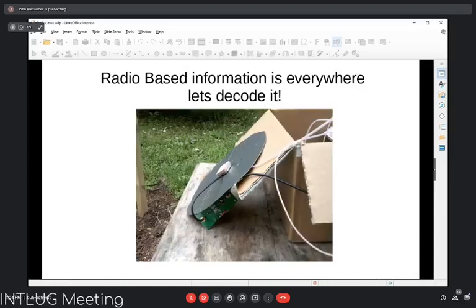So this is an example of the antenna they've used to pick up that information, right? This one's actually not, or certainly no dish, right? It's a GPS antenna, like some of these but a bit bigger, and it's just sitting on a bit of metal sheet to act as a ground plane. They're literally just a lump of metal, a sheet of metal, and the amplifier's there.